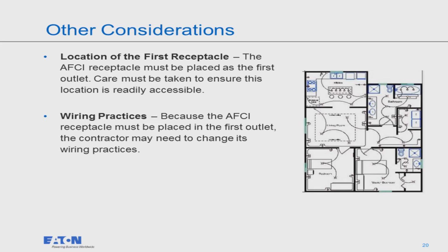So that AFCI receptacle must be placed at the first outlet. And we're only looking again at receptacles. We're not looking at lighting. So now you might be running separate lighting circuits versus receptacle circuits. So the wiring practices could really change when we're looking at the implementation of this code.